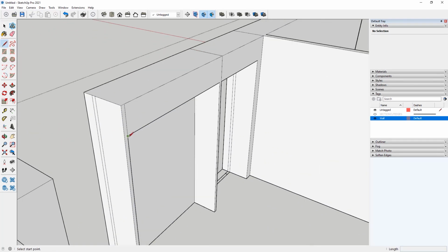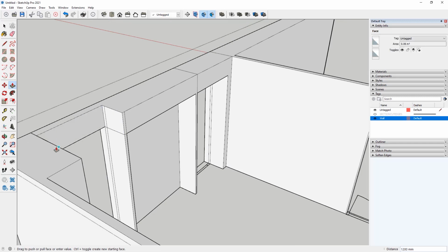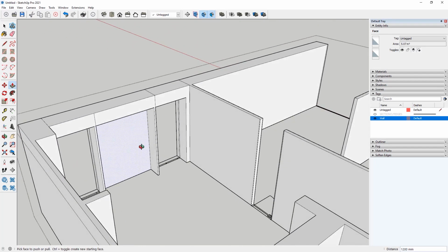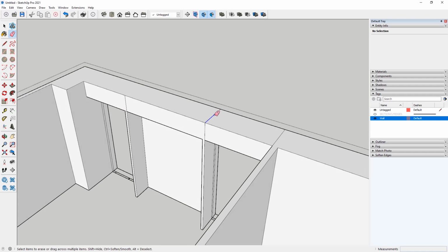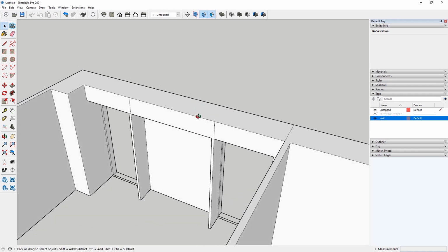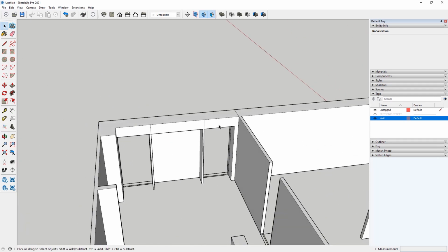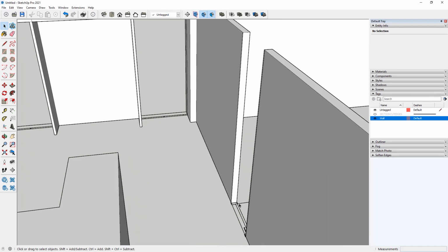The same in the last area, so we can extend the existing line and use it as a reference to add push-pull for the top. Okay, and this is how fast we can add the top wall, and always remember to use rubber to delete unused lines. We can do it with some plugins, or for example manually with the erase tool.